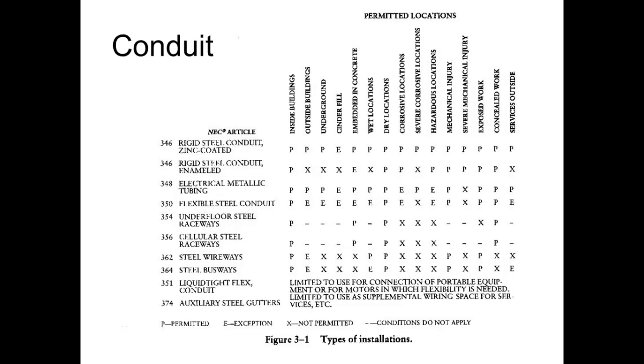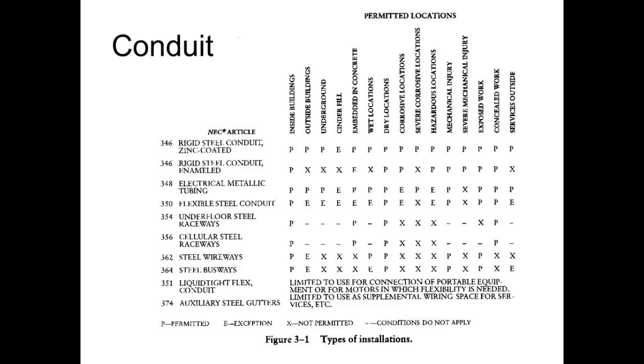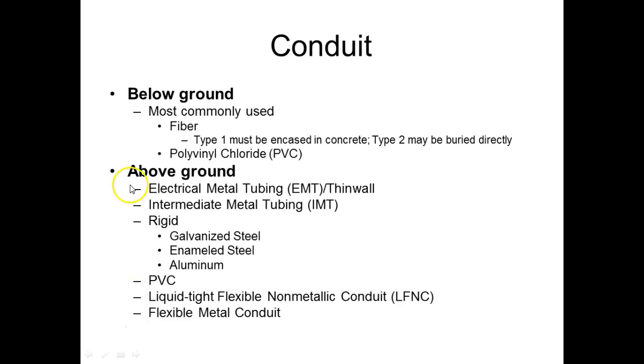Yeah, usually if you're going to run it through concrete, they usually run PVC through concrete, because the problem is the acids and everything in concrete will eat metal up. So that's why you don't ever bury metal in concrete. So you'll see PVC used in concrete. Oh, to put it in concrete? Yeah, it'll eat it. But you don't know what's going on there.